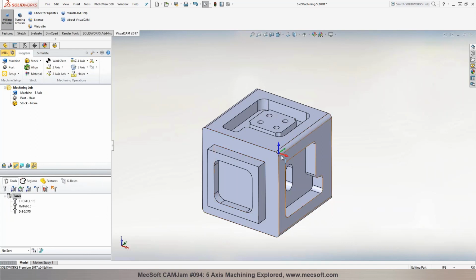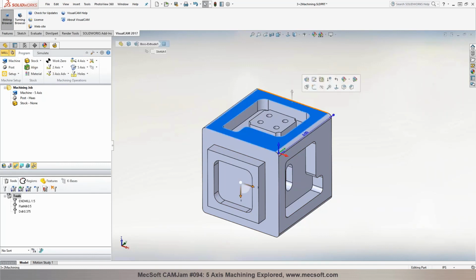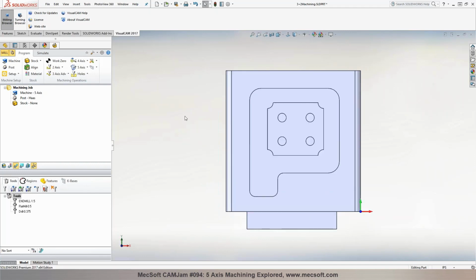Right, so now here we're going to go back and reset it to the world coordinate system, the same orientation. So when we want to start machining this part, we're going to basically place the block so that this feature will be looking down, through the machine tool as you want to mill this. So you have your X, Y, and the Z orientation, and the origin is over at this corner. Now we established that.